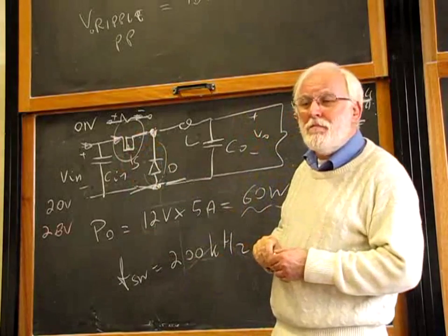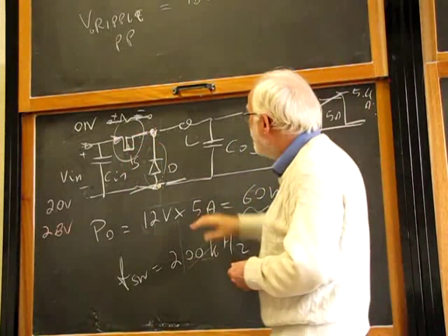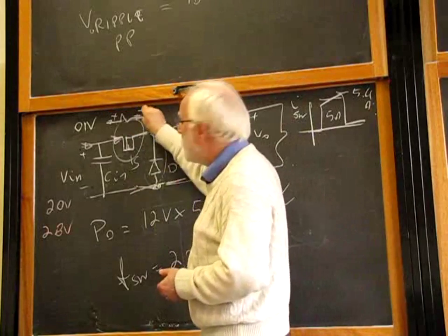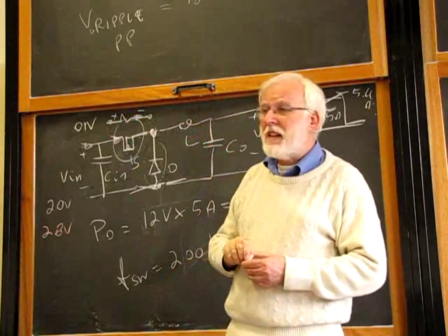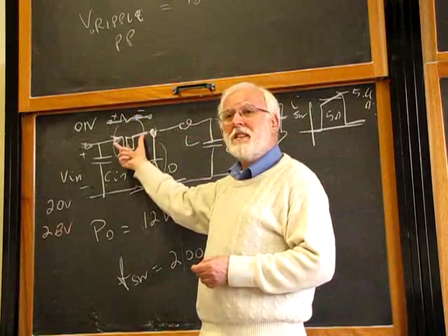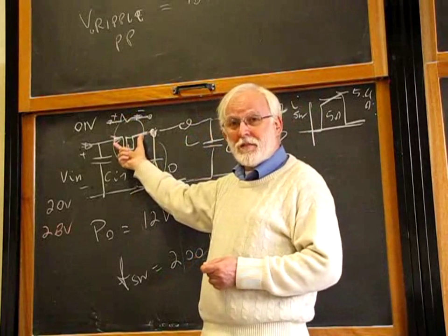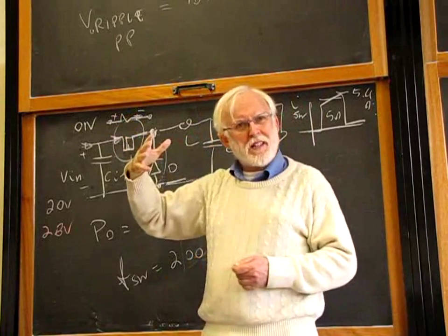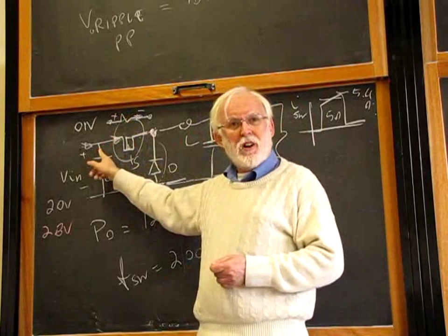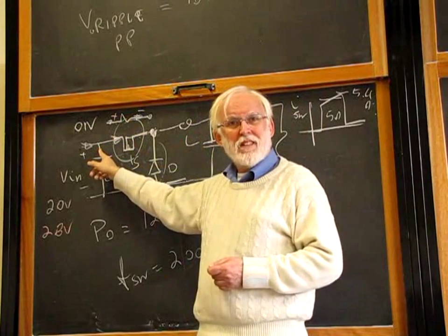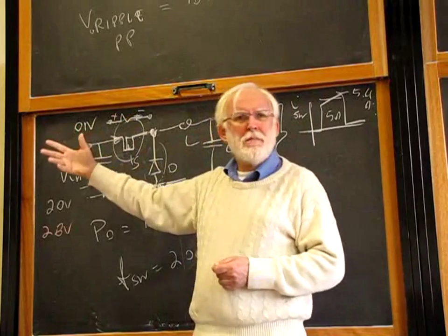So a better idea to determine how much voltage drop you want across the switch is to say something like, a voltage drop that is quite smaller, a couple of orders of magnitude less than the input voltage. One order of magnitude at least, maybe two.